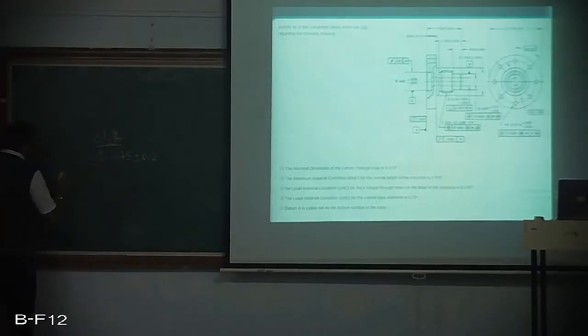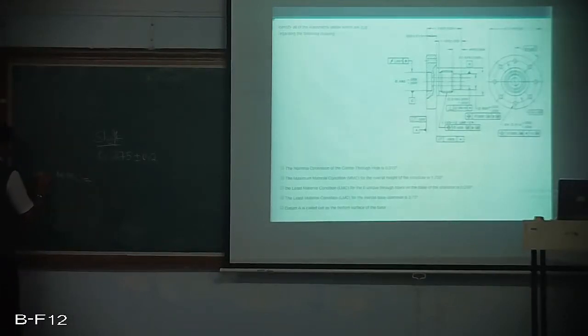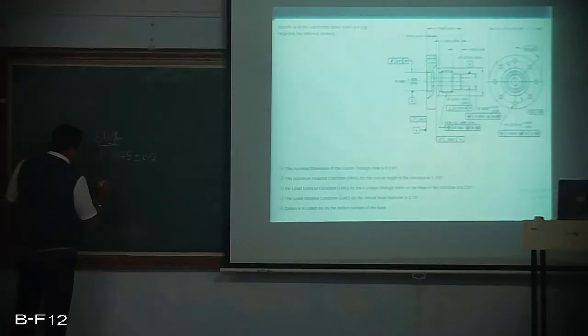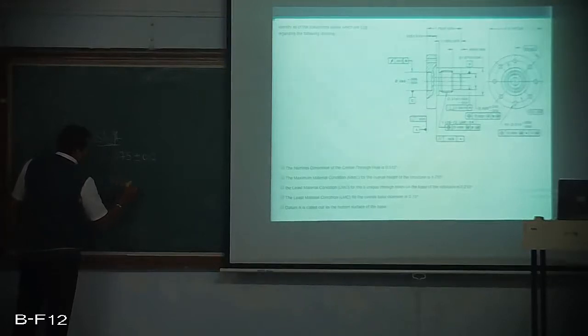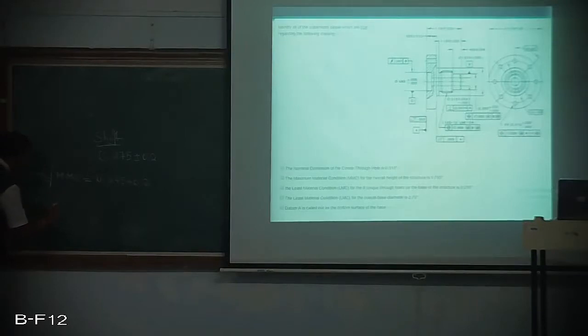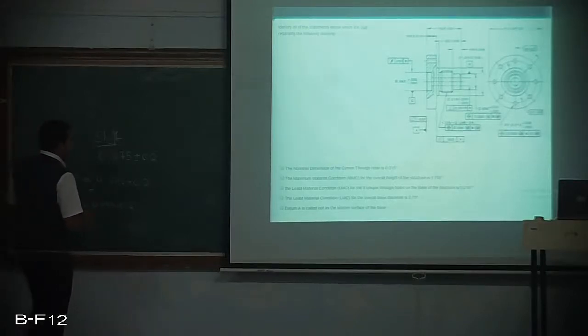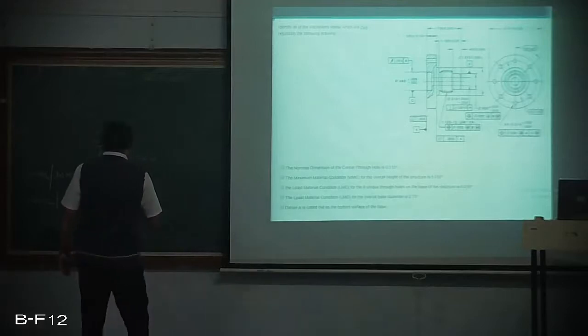Hence the maximum material limit is the upper limit, that is plus 0.02, and the least material limit is the lower limit, 2.75 minus 0.02.